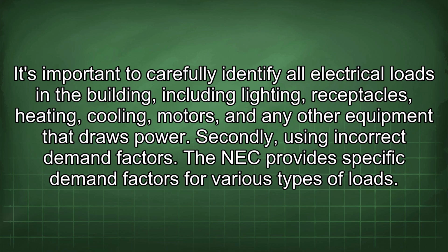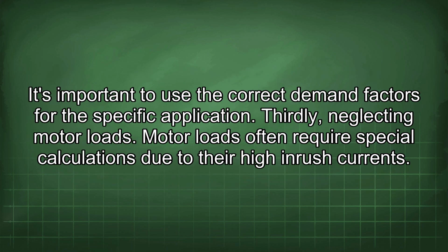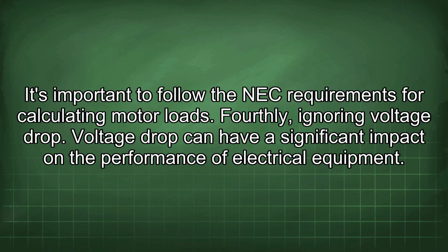The NEC provides specific demand factors for various types of loads. It's important to use the correct demand factors for the specific application. Thirdly, neglecting motor loads. Motor loads often require special calculations due to the high inrush currents. It's important to follow the NEC requirements for calculating motor loads.